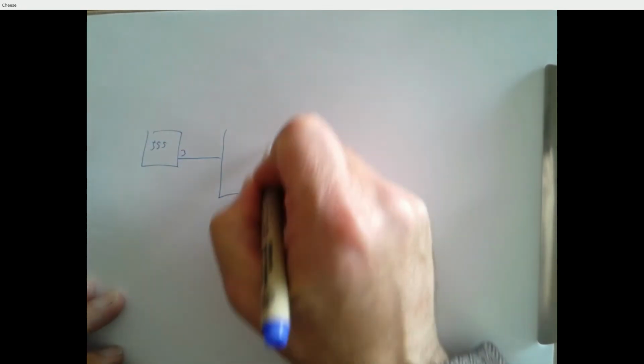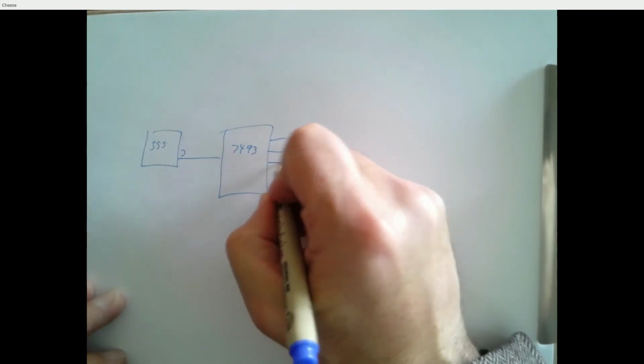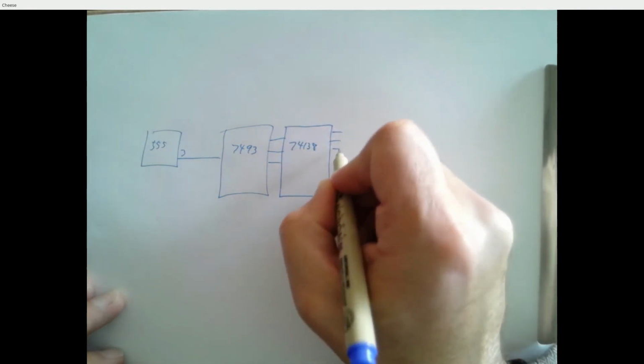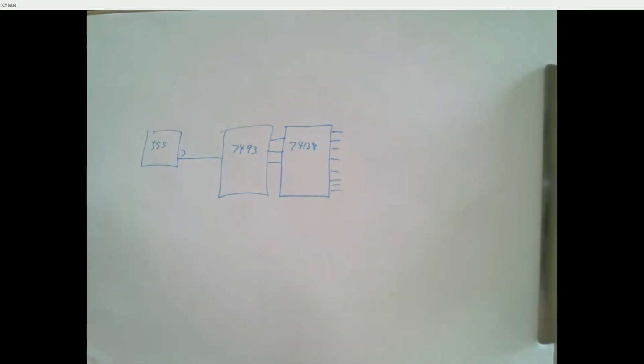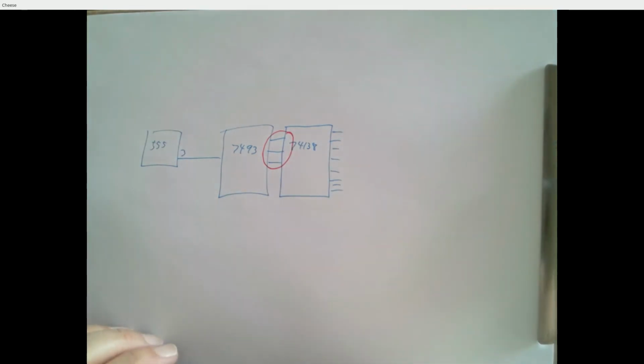It could be a wiring issue. It's definitely a wiring issue. I just need to go think about it. Yeah, you've got your 555. You've got pin 3 going into your 7493. You've got your outputs from here going into your 74-138. And you're looking at these outputs from your counter, and one of them's always stuck, right? Yeah. So I don't think there's an easy failure mode for that.